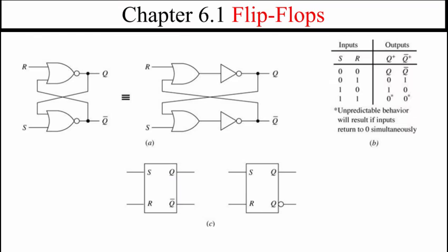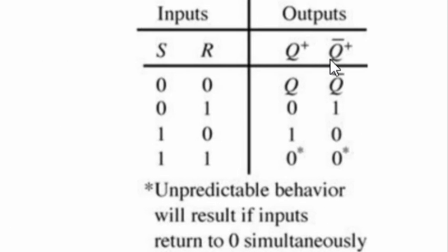All right. Okay, so here we see a summary of that playing around I did in Latches. Here's our NOR gates. Here's our reset. Here's our set. Here's the truth table. When both are 0, it remembers the previous state. So this is the remembering row. This is the remembering state.